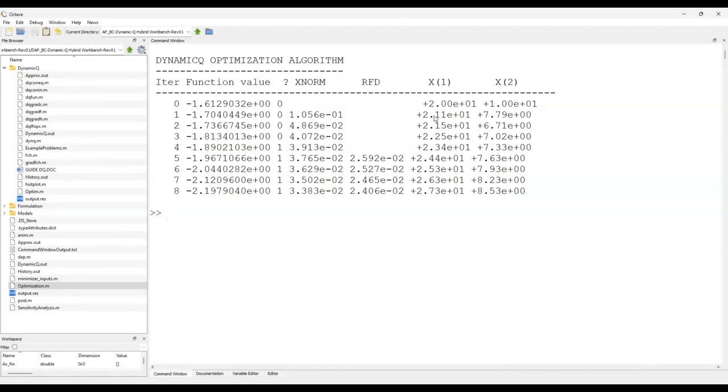It's just basically to show that for your move limit, which we now assigned as 1, the convergence behavior is quite slow. You can see over here it starts at -1, then it goes to -2, and then it basically stays at -2. Then it's going to go to -3, stay there until it reaches -4, -5. So it's going to take quite a while to converge on the tolerance that we want.